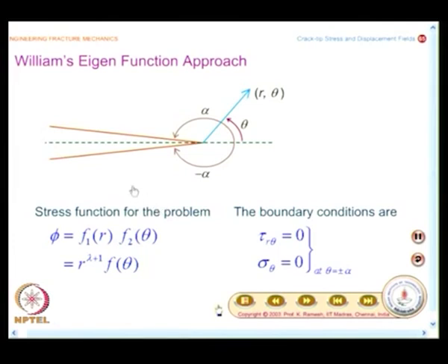The books say you are only talking about a uniform loading at that place. You are only worried about how the crack faces are. The crack faces are free, that is all you specify. Not only this, when you look at the solution, you will find this is a planar problem. The solution will automatically take you to a combination of mode 1 and mode 2.